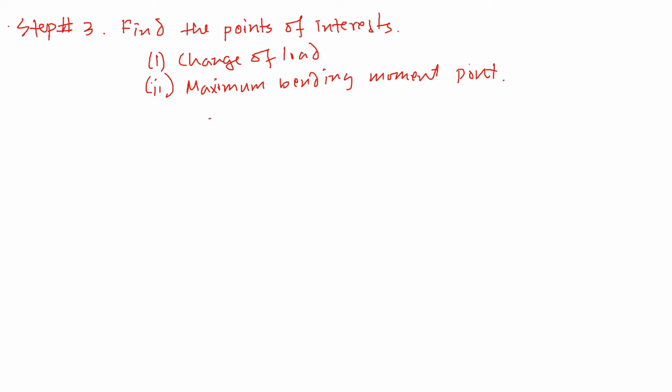This is typically found after drawing the shear force diagram. Wherever shear force is 0, moment is max at that point.